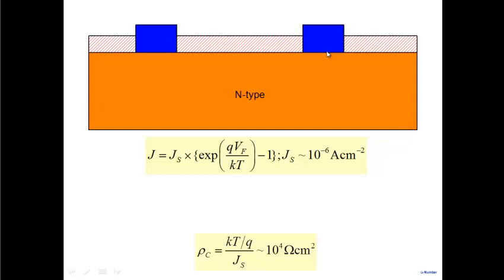We want all the voltages that you apply to drop across the semiconductor. So in this case, we are not interested in Schottky barrier diode. All we want to do is, we have an N-type semiconductor, we want to make a contact to it, and we are interested in the property of the N-type semiconductor, right? So we don't want any voltage drops to occur here, we don't want any voltage drops to occur here. Whatever voltage we apply, we want it to apply in this region, right?